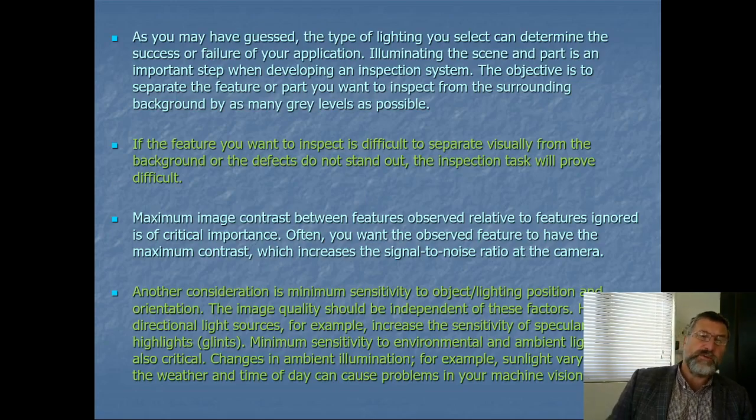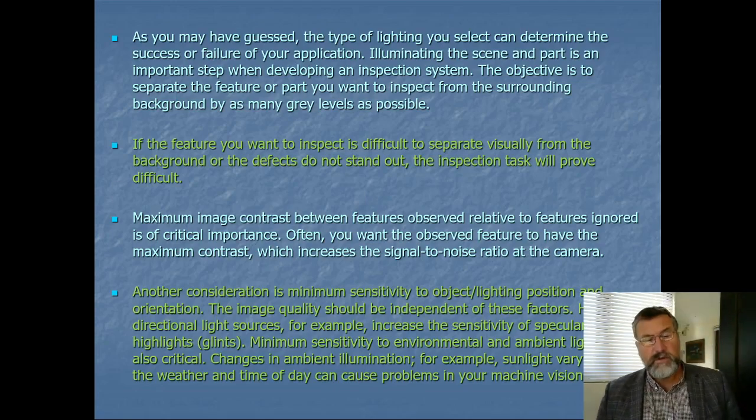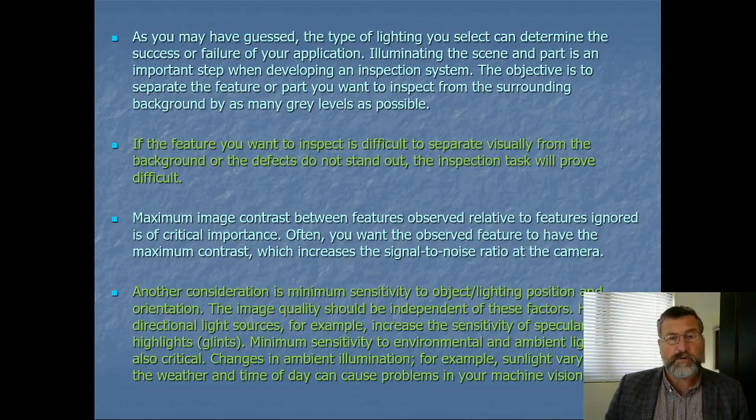And that's very useful because we can shine it at, say, an object, and we can scan it over an object or put the object on a conveyor belt. This is a standard technique in 3D machine vision to recover data from 3D objects by scanning them by laser, we call it laser triangulation. It's quite accurate. It has a disadvantage that the laser is quite typically a bit expensive. But it is accurate, and it's used quite commonly in industry.